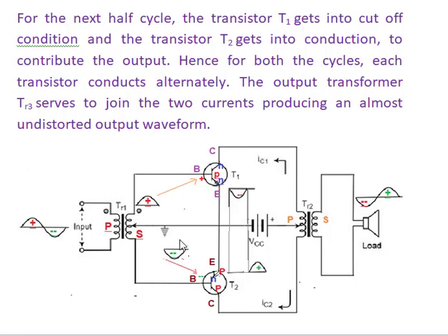At the same time, at the negative off cycle, the negative voltage is given to transistor T2. As it is a PNP transistor, the base is made up of N-type material. So the negative potential given here makes it forward bias. So the transistor comes under forward condition and T2 starts to conduct. As it conducts, the voltage flows in the collector of transistor T2.